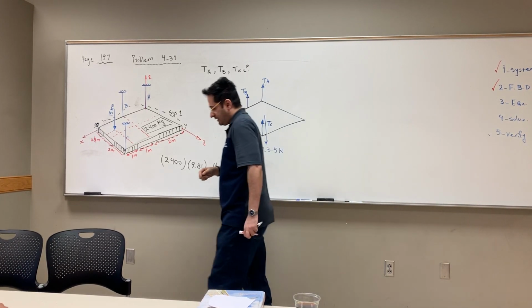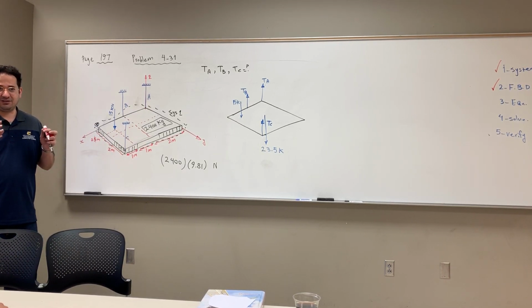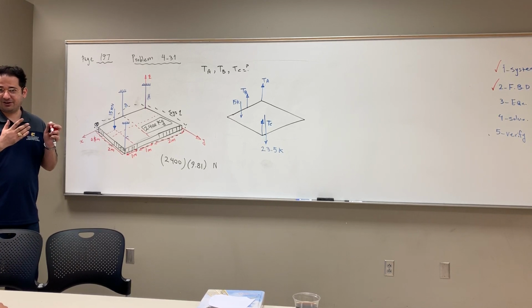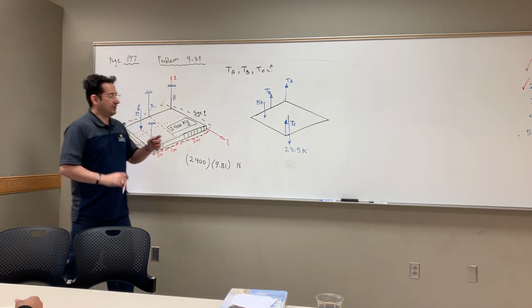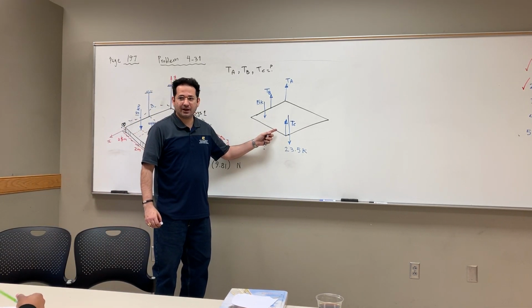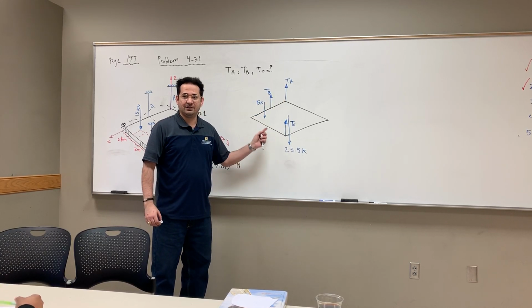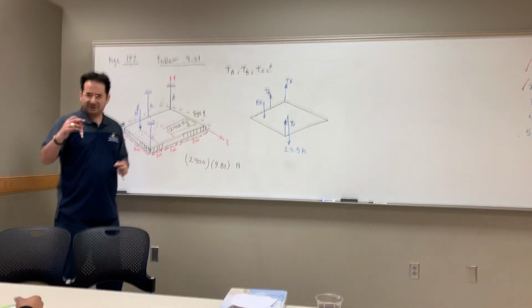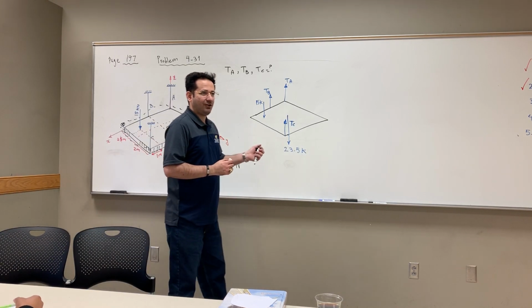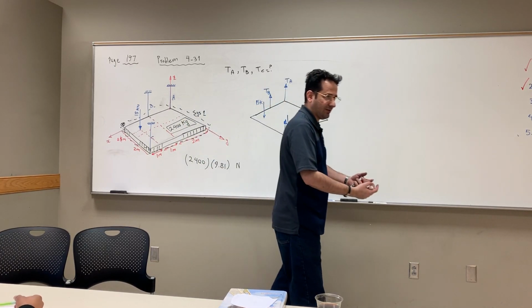Now, before we get our hands dirty in writing equations and solving, I do a feasibility study, to see if I can solve it or not. Now I ask the question, can I solve this problem or not? Yes. Why? Because the number of unknowns, how many unknowns do I have? 1, 2, 3. How many equations do I have? 6, because it's 3D, three-dimensional, right? 3 in force, 3 in moment, right? So yes, I have enough equations to solve for the unknowns. Now with high confidence, I go to the next step.